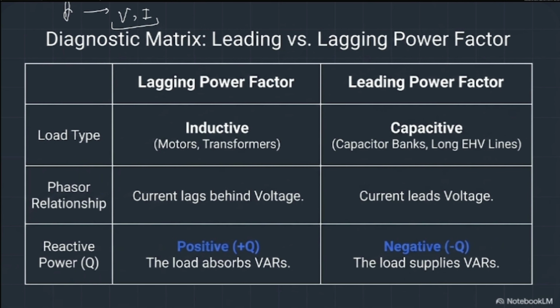Whenever you have negative or positive, you don't have any problem with the active power, but you do have a difference in the reactive power, because that difference is going to show the characteristic of your total load itself. Either it's going to be capacitive or inductive. By the way, inductive means that it's about the inductor. You see it in motors and transformers. Capacitive means capacitor banks or other things. So capacitor and inductor were two other important components in the circuit rather than the resistive itself.